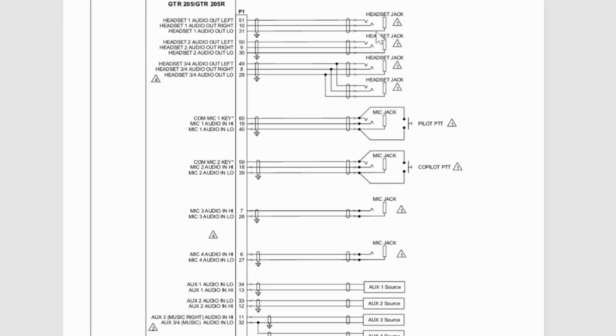And if we look further, you can see these little chevrons and a rectangle and a number 1, and then same thing that we saw last time, the little loops with the terminations on the bottom. So this indicates a headset jack. If you look inside a headset jack in aviation, you'll see kind of like prongs, kind of like what you're seeing here.